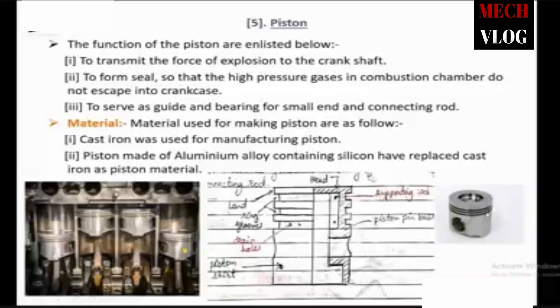Please reply. Can you see these grooves? Yes, sir. Okay, so this piston has three grooves. That means we have three compression rings. The first ring is called the top compression ring, so that will come on the top, in the first groove. And the second ring is called the intermediate ring, and the third ring is called the oil control ring.